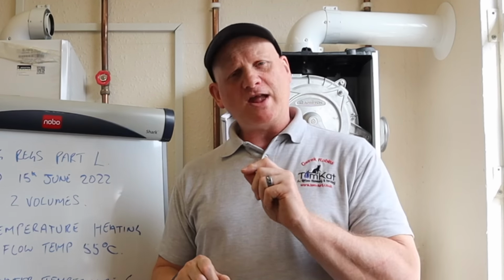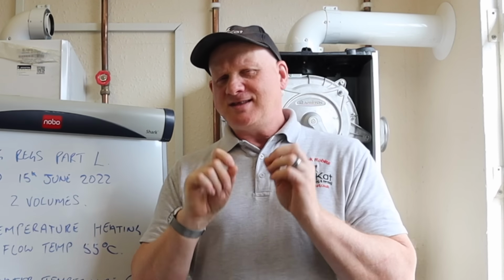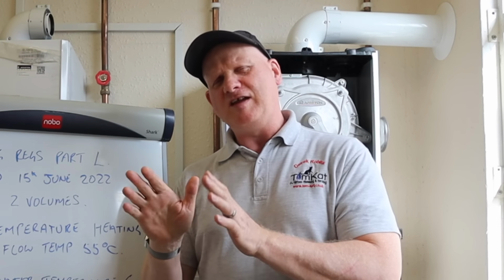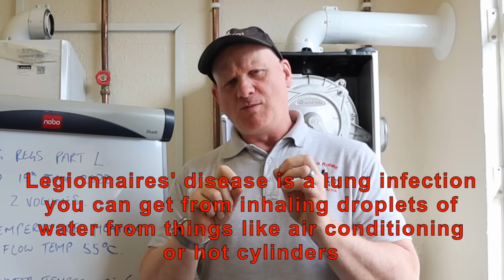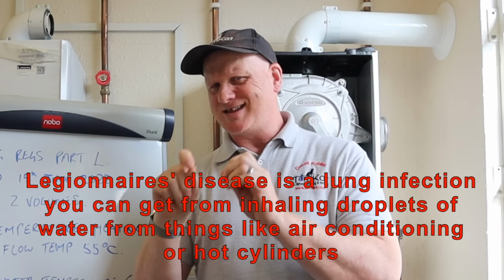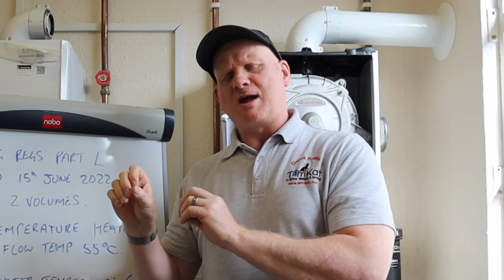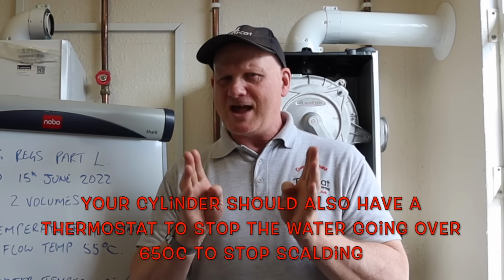If you've got a regular boiler or a system boiler and you are heating your water by a cylinder, that cylinder water temperature within it has to be kept above 50 degrees because of Legionella. And normally we store water in the UK between 60 and 65 degrees, because it gives us that optimum temperature when we're running the water, and it recovers quickly so you don't run out of water. So you've got to bear that in mind.